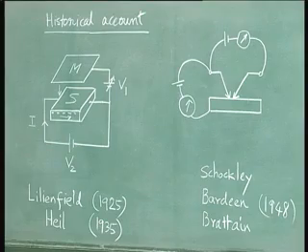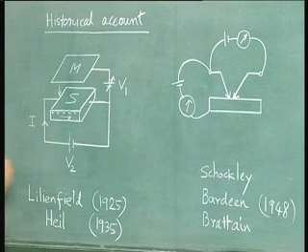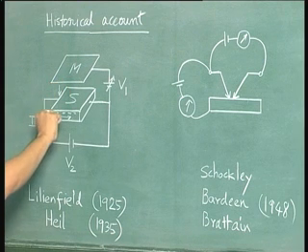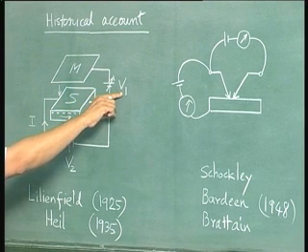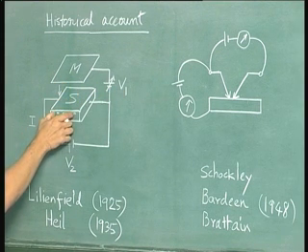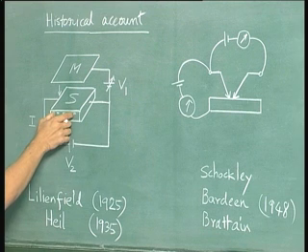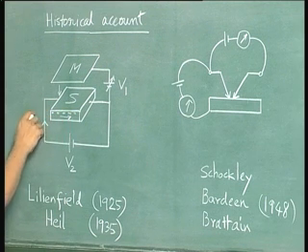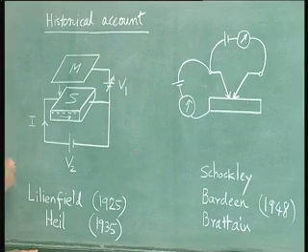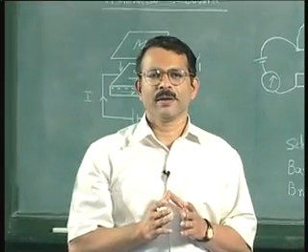Specifically, what they found is that a practical device realized according to this idea had very little current modulation by the control voltage. If you make a simple calculation based on a capacitance model, for a certain change in voltage V1, you expect a certain change in the conductivity by the simple capacitance formula. Then using that change in conductivity, you find out the change in current for a given voltage. That was the expected change in current, but practically the device hardly showed any change in current. This was the problem.